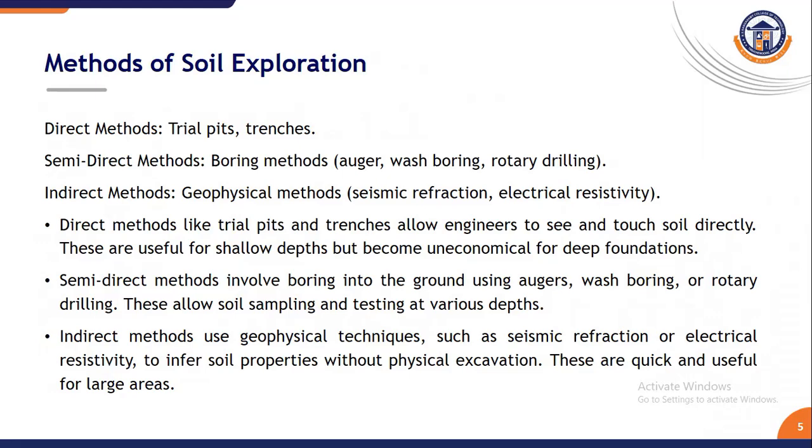The direct method involves trial pits and trenches. The semi-direct method involves boring, like auger boring, wash boring and rotary drilling. The indirect method uses geophysical techniques like seismic refraction and electrical resistivity.